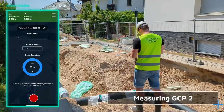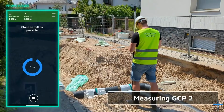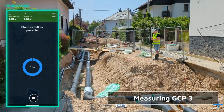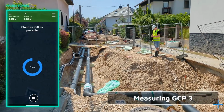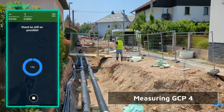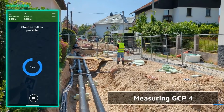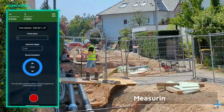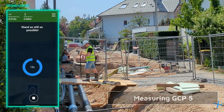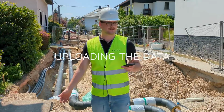Okay, and we are collecting now point by point. When you're measuring, this is still the Reach RX model, so you need to look at this bubble that's in the center, that the pole is vertical. With the new model, even this is not needed anymore. Okay, so we are done.